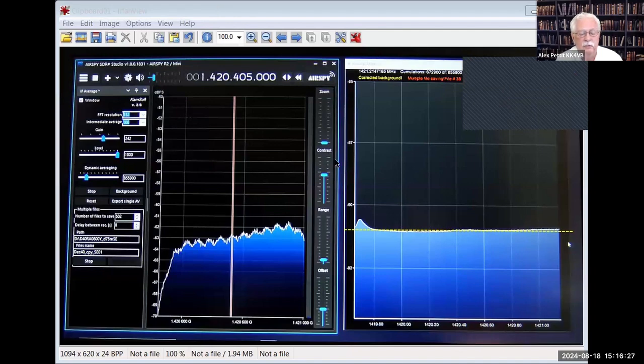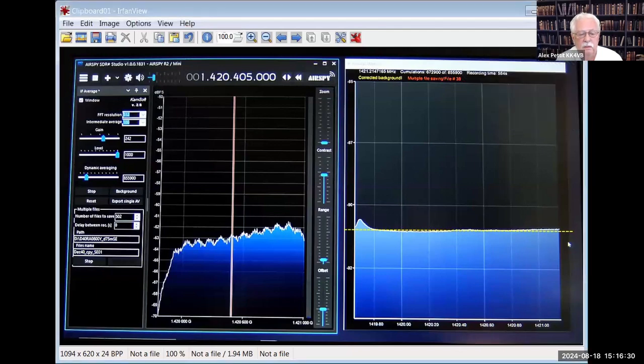I'm running a drift scan on a new system, but if you exclude that little rise to the very left, which is an issue associated with either using a 50 ohm calibration resistor and then going to the patch feed on the antenna, the rest of it is a flat line. And I did the initial background calibration when it was about 80 degrees outside, and now it's up to 92. And I guarantee you that the higher end frequencies would be up or down about 3 dB, and that lower end would have shifted. So I have succeeded.